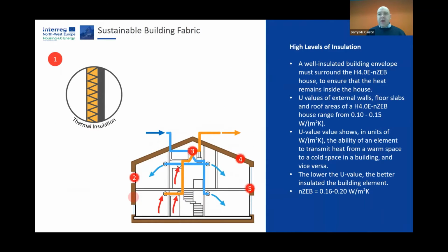So again, this reiterates a little bit of what I was saying, and it's no harm to just go over it again. The high levels of insulation, and I talked about this, the U value that you're aiming for is about 0.15. What's really interesting is that's not a prerequisite. You can have U values outside of that 0.15, and that's what's really good about these standards. You can make it up elsewhere. It's not as hard and fast and rigid as people believe it is.